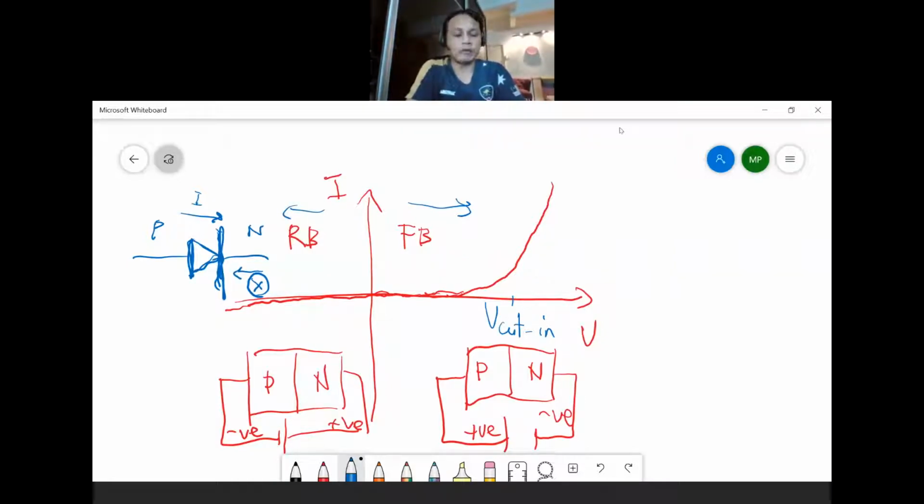However, if you look at the diode equation, J is equal to J naught exponential QV over KT minus 1. If you increase the voltage into the negative region, you will eventually have J equal to negative J naught. J or I, if you want to plot I, then I equals negative I naught, right?